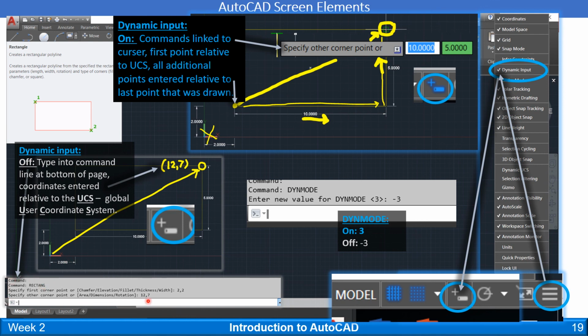So you can see down here in the command line what I type in when my dynamic input is off. And sometimes it's easier to think of things relative to your previous point. Sometimes it's better to map everything out relative to your coordinate system. So this is something that I use a lot, at least. You turn it on and off just depending on what you're drawing and what it's easiest to figure out dimensions off of.